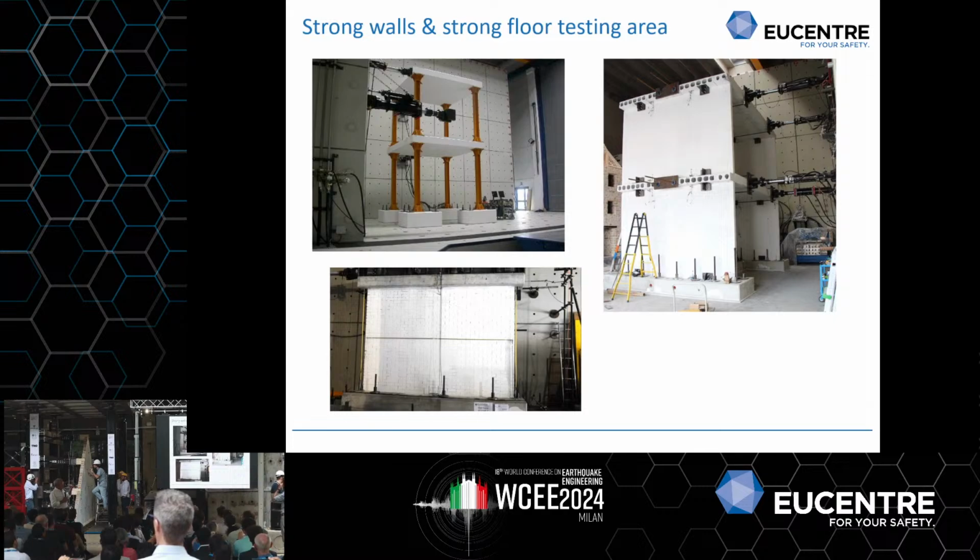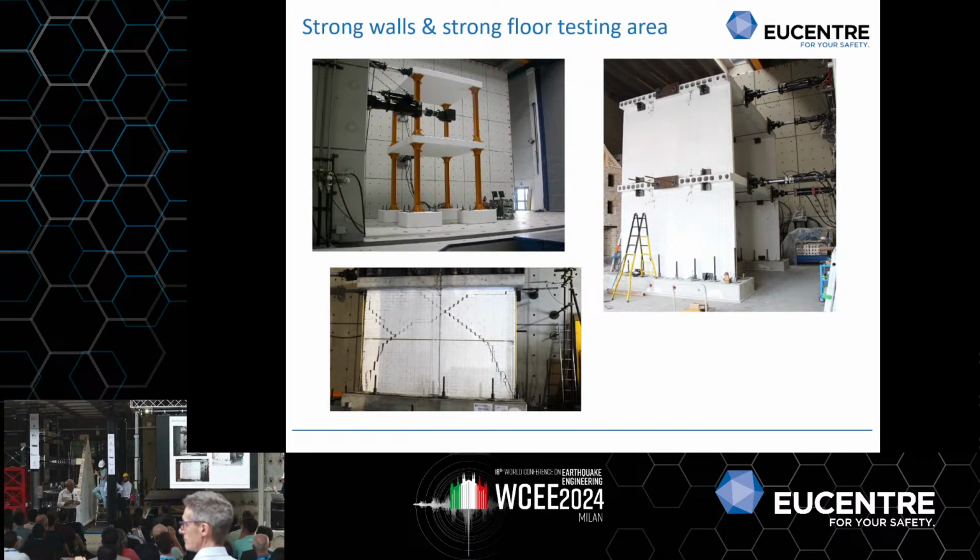In the same laboratory on the other side, we also have a three-dimensional reaction system which is made with cubes that are connected only by means of post-tensioning cables. So they are prefabricated cubes, 2.4 meters side, and this has permitted to have a very precise, very accurate structure.